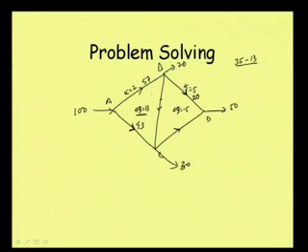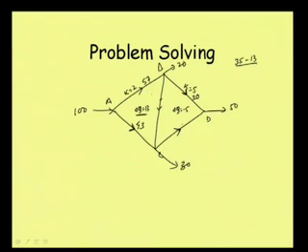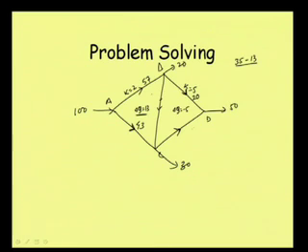And then here, the earlier assumed flow was 35. So now this new flow will be 35 here, but the flow is anti-clockwise, and the correction is negative. So from anti-clockwise we will have to deduct. Earlier this flow was 35, so now it will be 30 here after correction. So it will be 30.